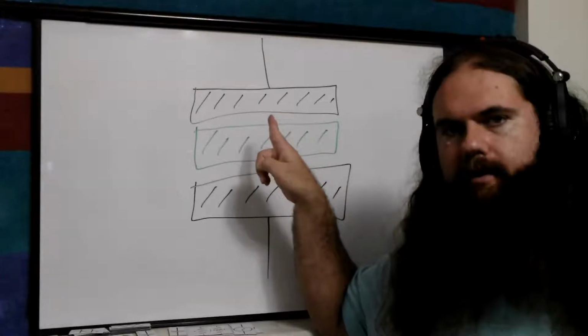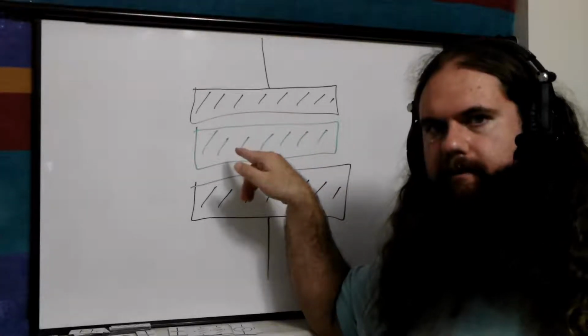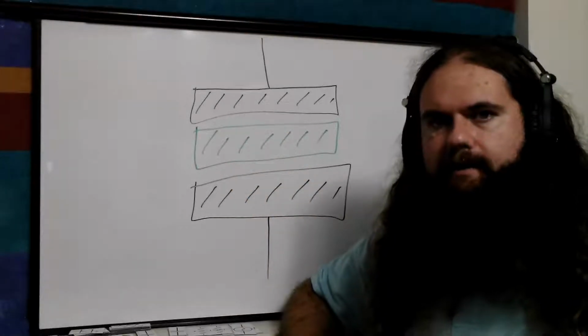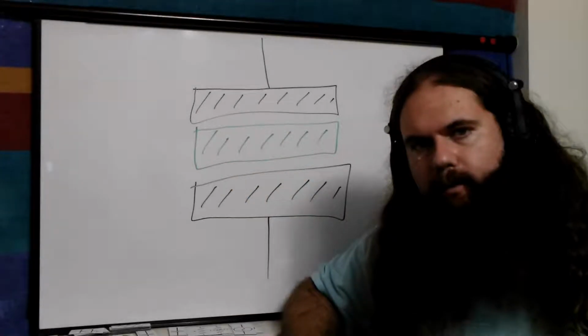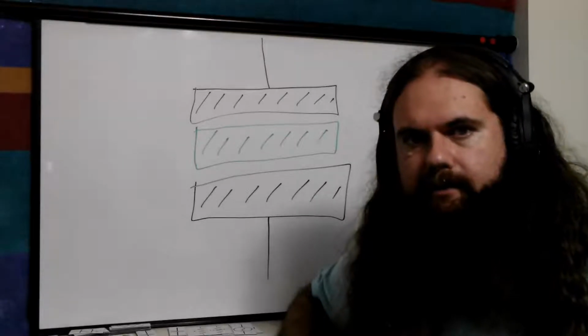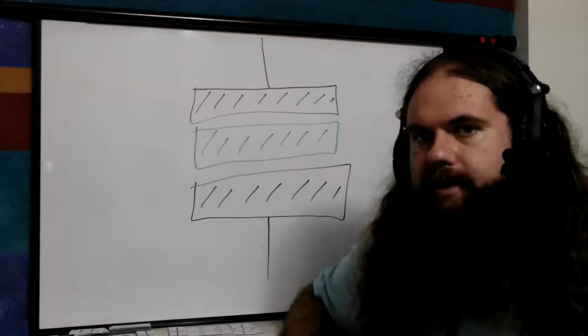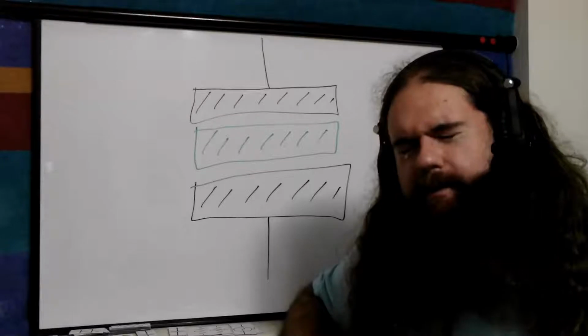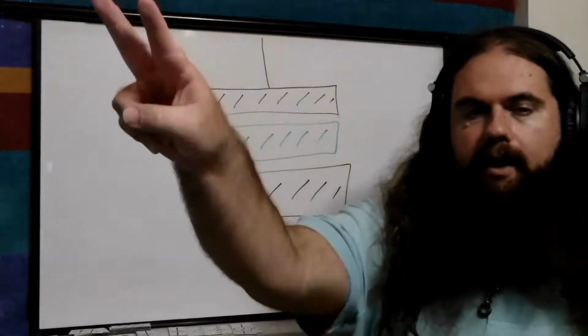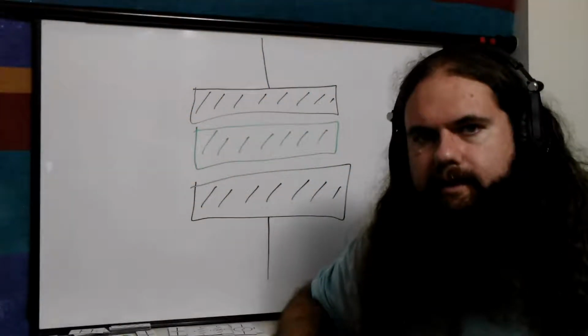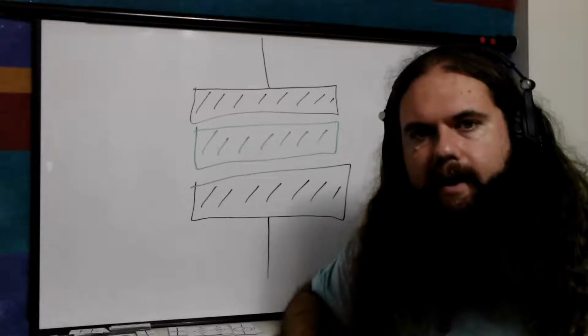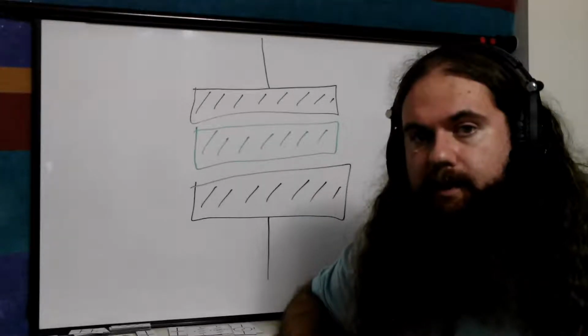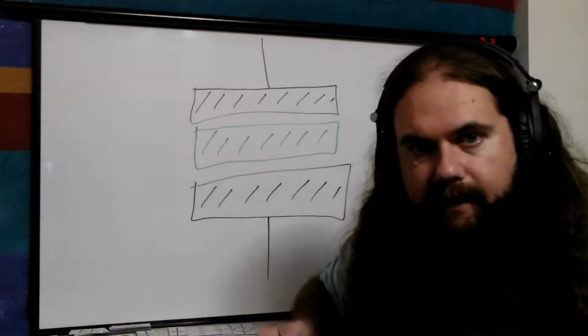And that is actually one of the cool but really annoying things about capacitance in general. Anytime you have two conductors with an insulator between them, any two conductors that just happen to be nearby, you have capacitance. It's sort of like how wires have resistance and we ignore it, but it's really there and it sucks. But obviously that's not something we can get rid of. For example, high power lines. You've got two wires carrying huge amounts of voltage and current between your house and the power company. And there's capacitance between those wires. And that's one of the things they have to engineer for.